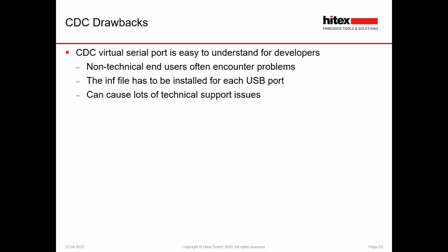The COM port has to be reinstalled if they plug into a different USB channel. So it can cause all sorts of minor technical support issues. It's very good if you've got a technician connection and you just want a serial port onto a device, but you need to really think it through if you're going to use this as part of a standard product.